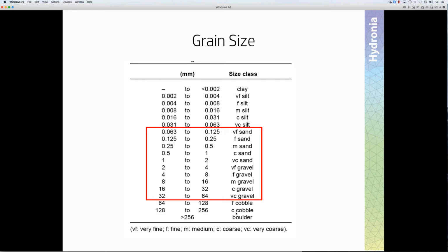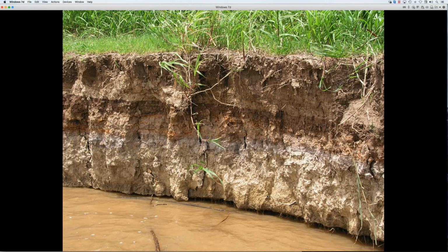Now, in general, in riverine environments, we are dealing with a range of sediment that usually goes from the very fine sand range to the gravel size. Although, of course, if we need to model very fine sediments, we can do that too. But there are some situations where this very fine sediment requires cohesive treatment. So they behave as cohesive sediment and they need special treatment. So this is the range we are usually covering in sediment transport in riverine environments.